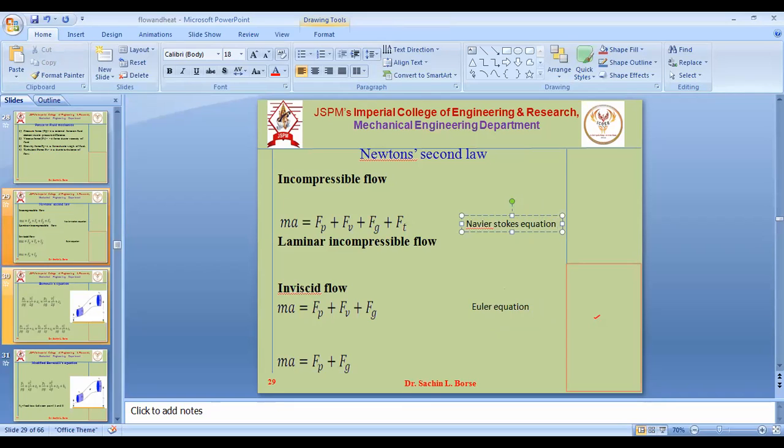Okay. So we generally don't use the Euler equation because the viscosity effect is always there. This viscosity effect is less at high speed for aeronautical people. So earlier, when there were limited resources, people were going with what? Euler equation. But people don't go with the Euler equation now, they go with the Navier-Stokes equation. And Navier-Stokes equations are three, one in x direction, y direction, and z direction.